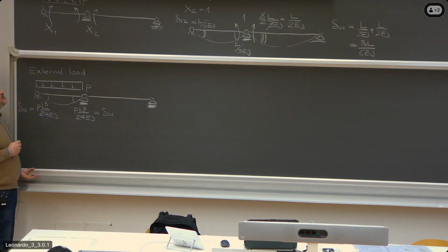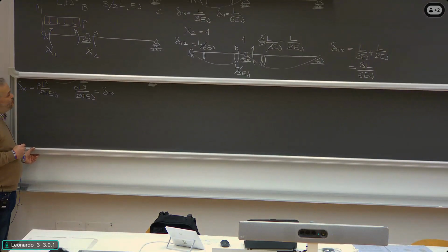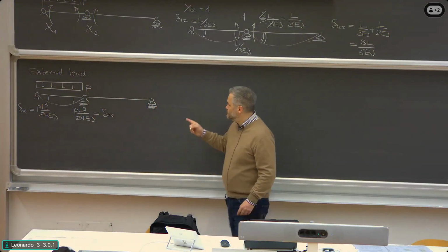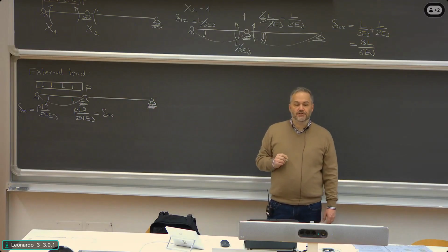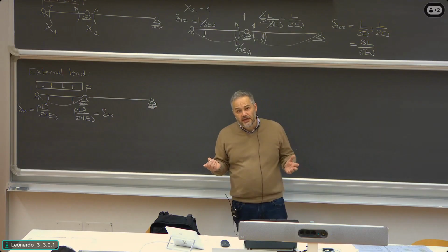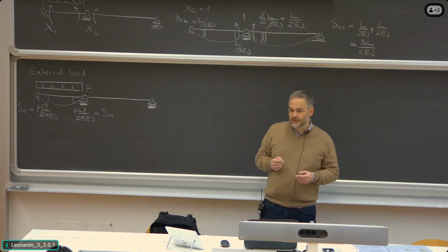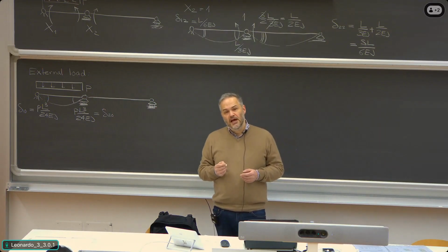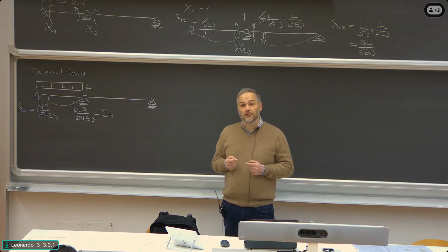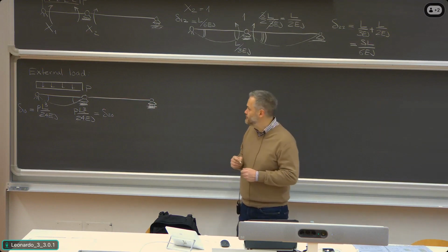So this basically leads us to the core of the problem, which is to look now at the compliance equations. We know that in statically indeterminate structures, equilibrium equations are not enough. So to solve the problem, among all the possible equations which are in equilibrium, we choose the ones that are also respectful of compliance. What does it mean?